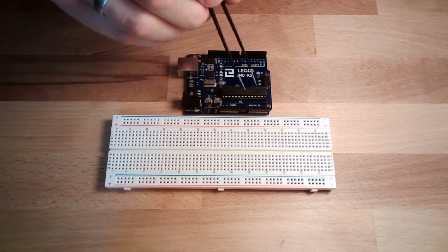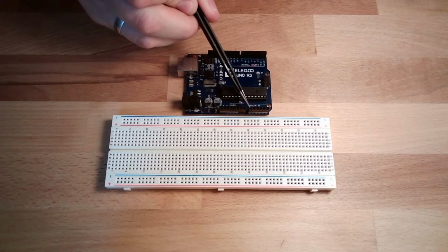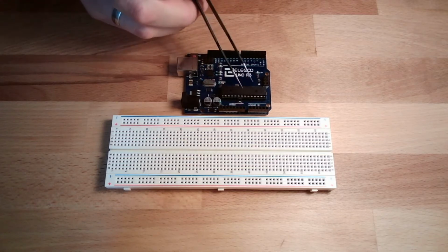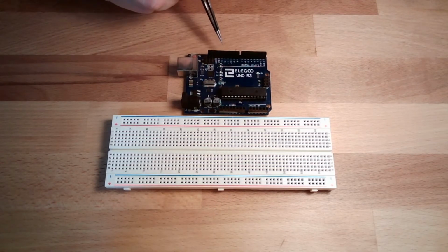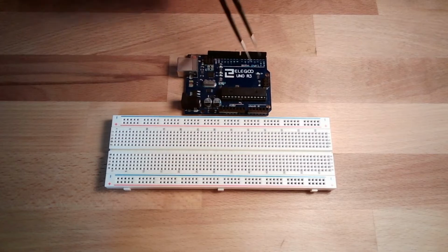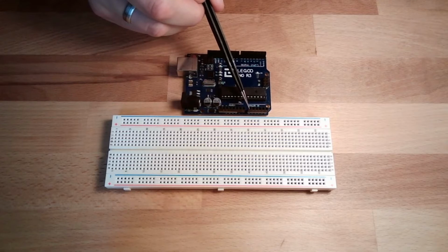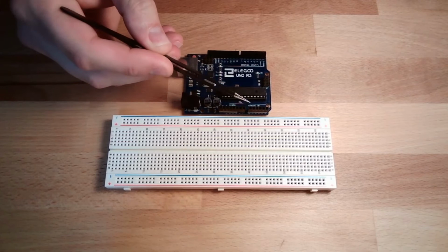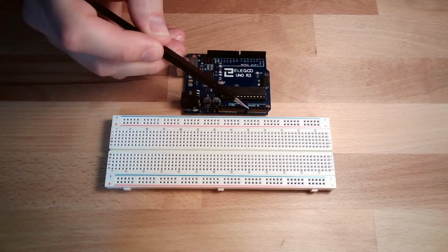Each input can handle usually between 0 and 5 volt. If you want to use another voltage level, please refer to the specs. There is also a reference voltage input here. You could connect it. However, out of the box, we are using 0 to 5 volt here. But in difference to the digital inputs, we are not using exactly 0 and exactly 5 volt. We are using something in between. So we can use whatever between.